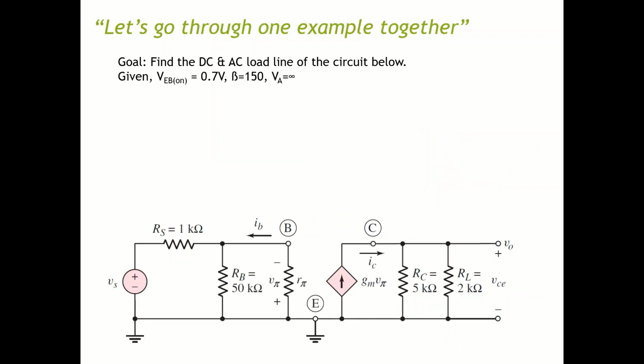So first of all, if we consider the capacitors acting as short circuits, we can convert our original circuit into the equivalent hybrid pi model. The current directions and voltage polarities in the hybrid pi equivalent circuit of the PNP transistor are reversed compared to the NPN device.